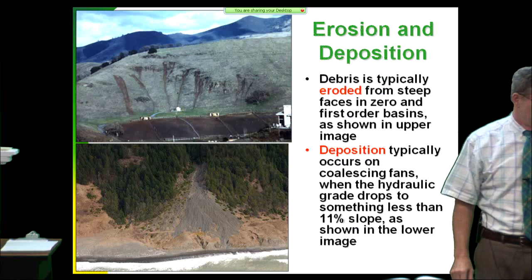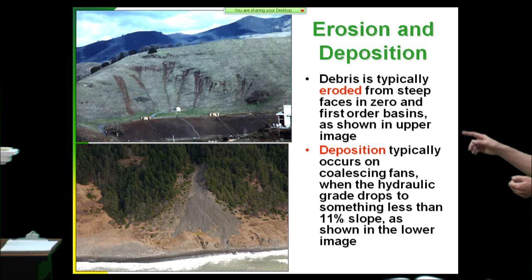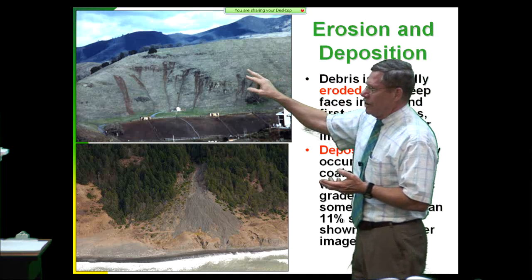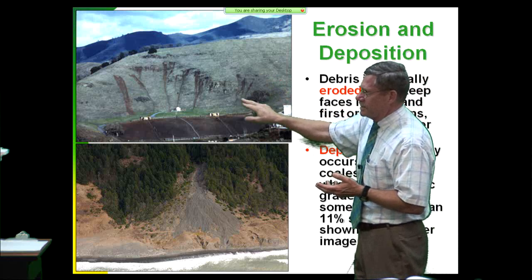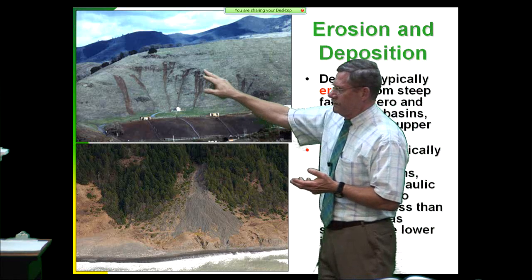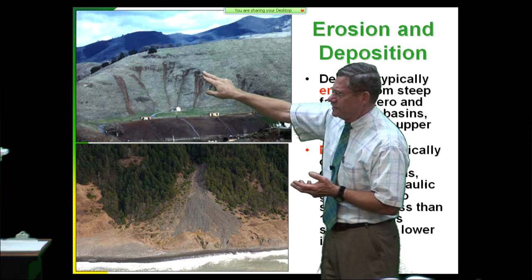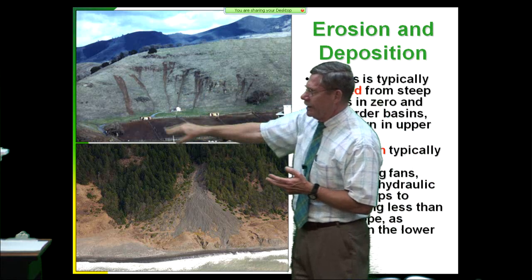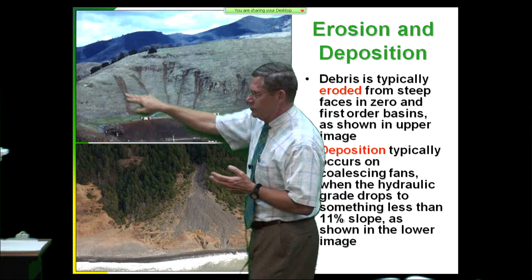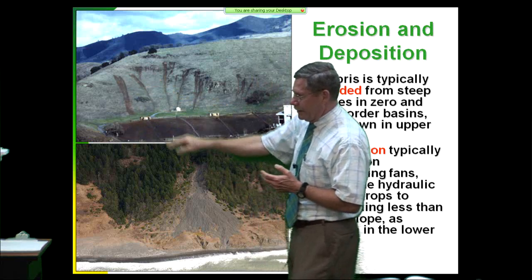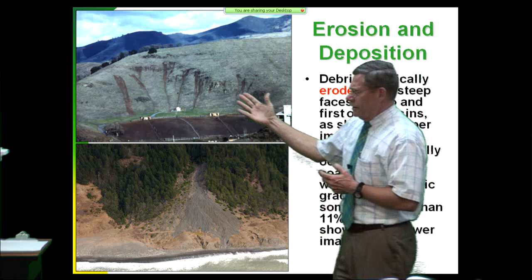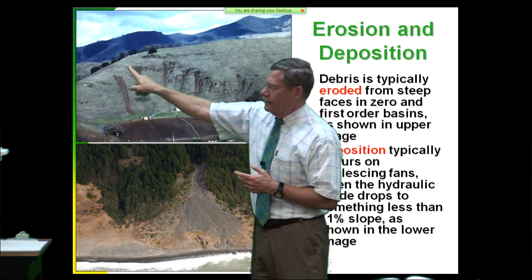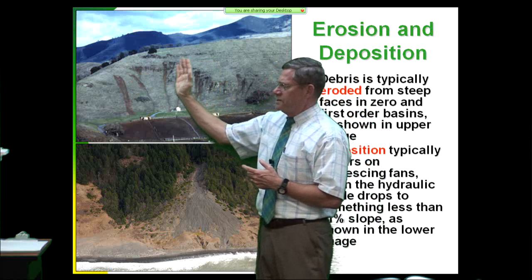All right. So what does it look like? Typically, when you have these storms and you have high intensity, long duration, you just see lots and lots of little pockmarks. Lots of little places where the pore pressure got too high, and boom, it vomits onto the slope. Here's another one, and another one, and another one. There's two real nice vomits right there coming down. And you notice here, this is all clay material, shallow bedrock right underneath, and very, very steep.